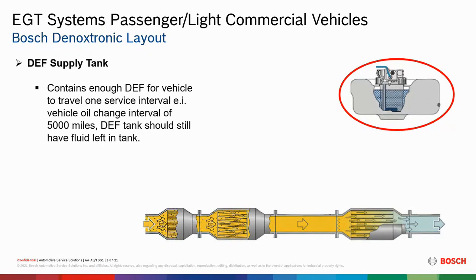However, some of them didn't want to take the trunk room away, so what they did was they put tanks, maybe multiple ones, in the rear behind the passenger seat and tried to fit them in here or squeeze them in here. Well, some manufacturers put a second tank above the first tank, and the lower tank is the fill tank. So in order to get fluid to the second tank that's above the fill port, you had to pressurize it.